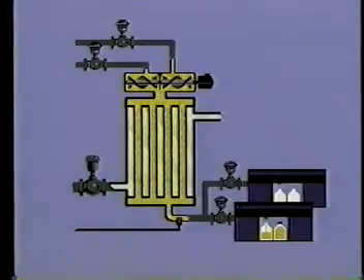The proportional action controller did a good job when the plant operated just one bottling machine. When the second bottling machine was started, however, something unexpected happened. Now the flow through the heat exchanger was doubled, but the control valve at that time was admitting only enough steam for one machine. Therefore, the product temperature dropped.